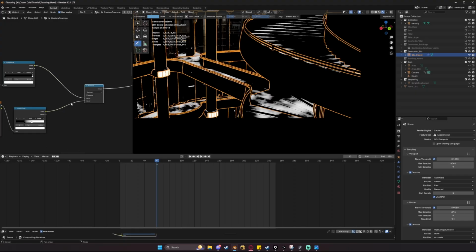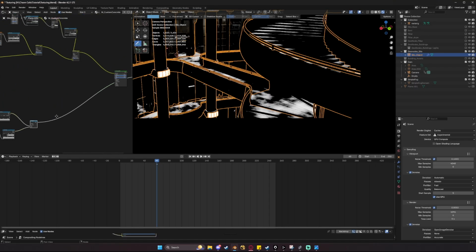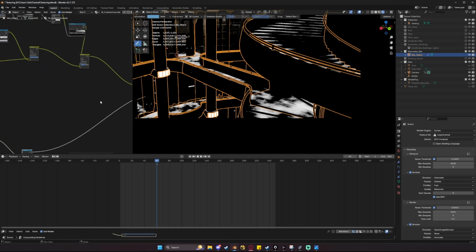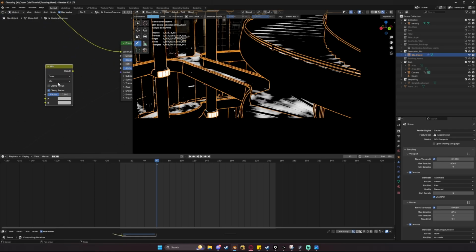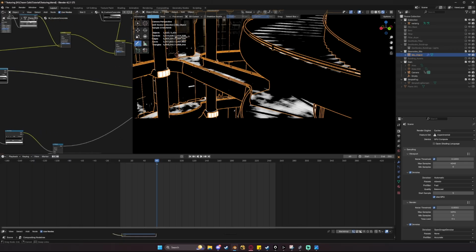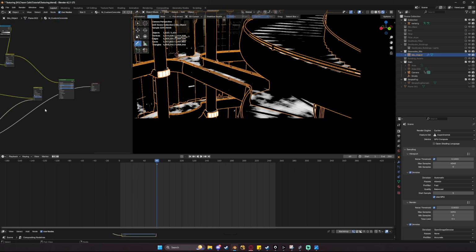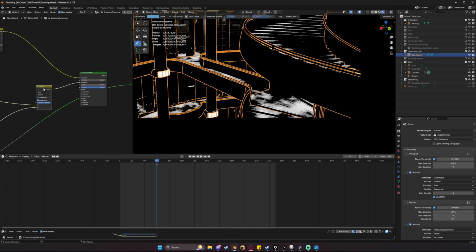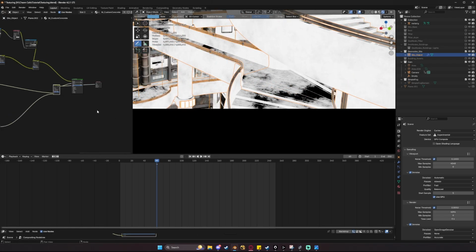So this is just going to leave us with our puddles, and all we need to do is do the exact same thing to our actual roughness path here. So instead of doing a mix, we'll do mix color this time. We'll set this to subtract with a value of 1. And I want to take our original roughness map and have it subtract our secondary roughness map. And if we look through this output, we can see that we're left with just the puddles, setting it to black.